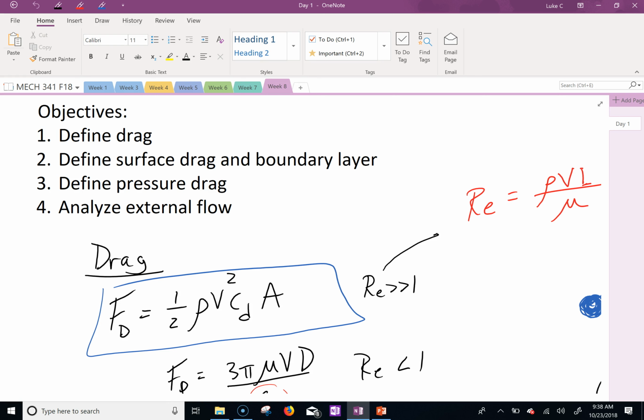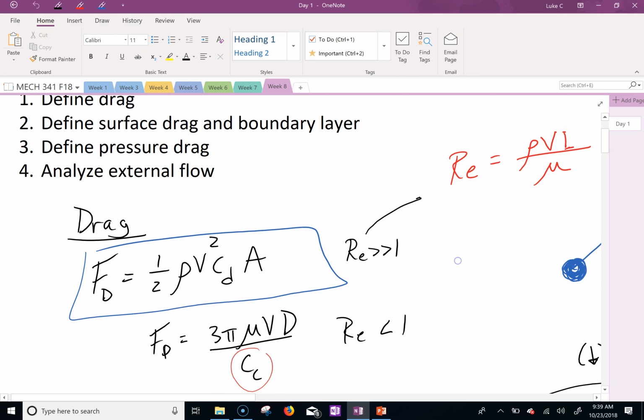And they're combined to get this overall drag equation, which is right here, which is 1/2 rho v squared CD times A. All right. And in a minute here, I'm going to talk about how to find CD, just the table values, and some other equations that we can use. Okay. So that is the fundamental equation for drag if you have high Reynolds numbers. Okay. And the Reynolds number was given by rho VL over mu.